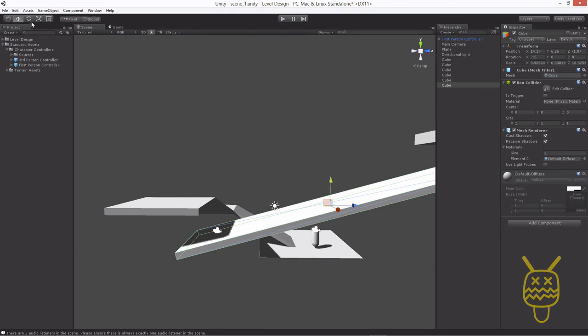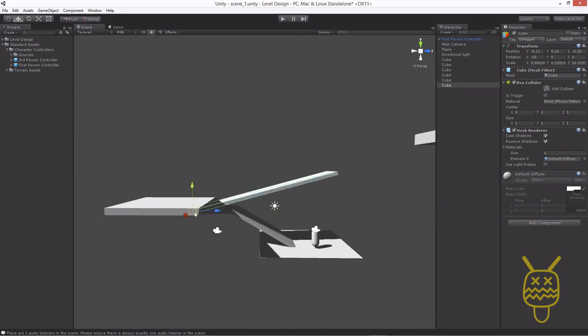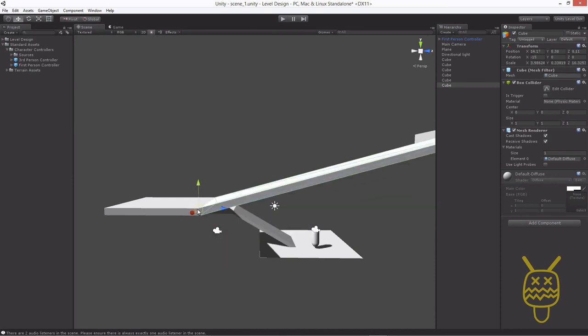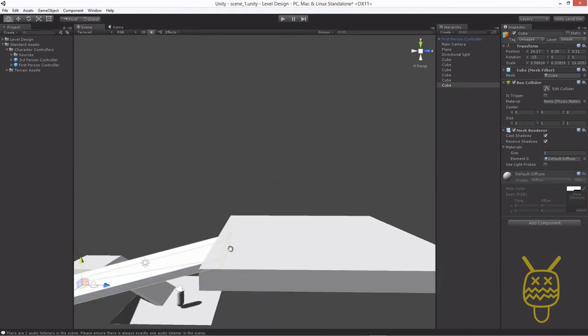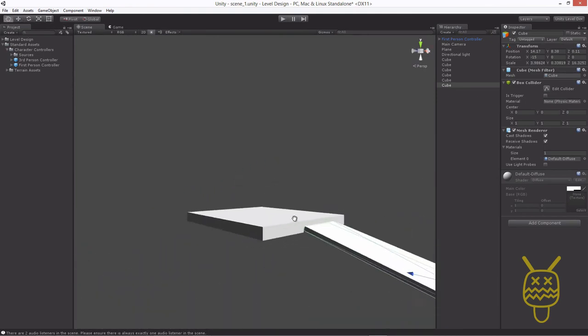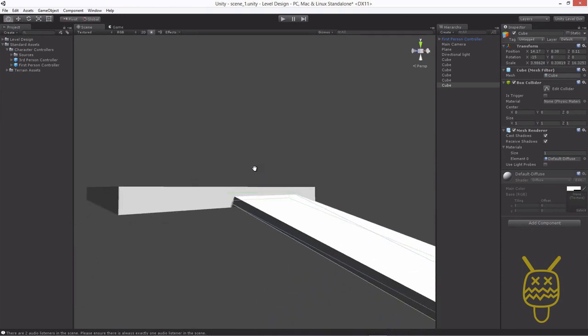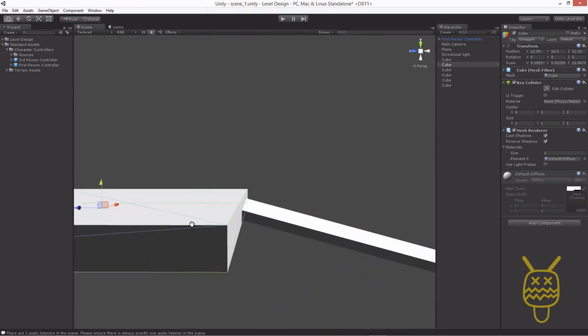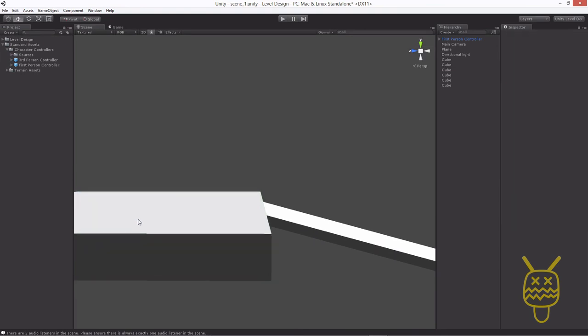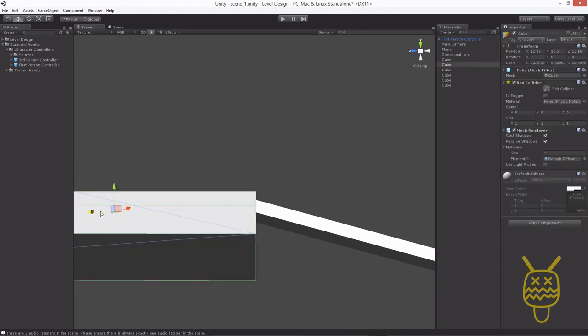So I'm going to change to my Move tool, holding V down. Again, we'll just hover over these, left click on that vertex corner, and then move your mouse all the way up to there. And if it jumps around on you, don't worry about it, because it's simply looking for different vertices in the scene, so you don't have to worry about it messing up or doing something weird. Just keep moving it until it gets to the vertex point you're interested in.